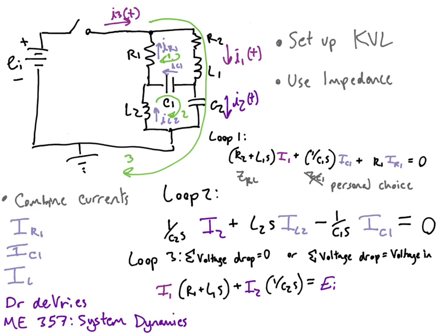then we have IR1 plus I3 is equal to I1. And in doing so, we can say that IR1 is equal to I1 minus I3. We could do that with C1, I1 minus I2, and with I2 minus I3. So for each node, we can say current going in is equal to the current going out, making sure that we end up with only as many currents as we have loops. Again, that's a step we should do in some order to help us solve these problems. The steps I'm giving, you can do them in any order. I just chose one to move through it.